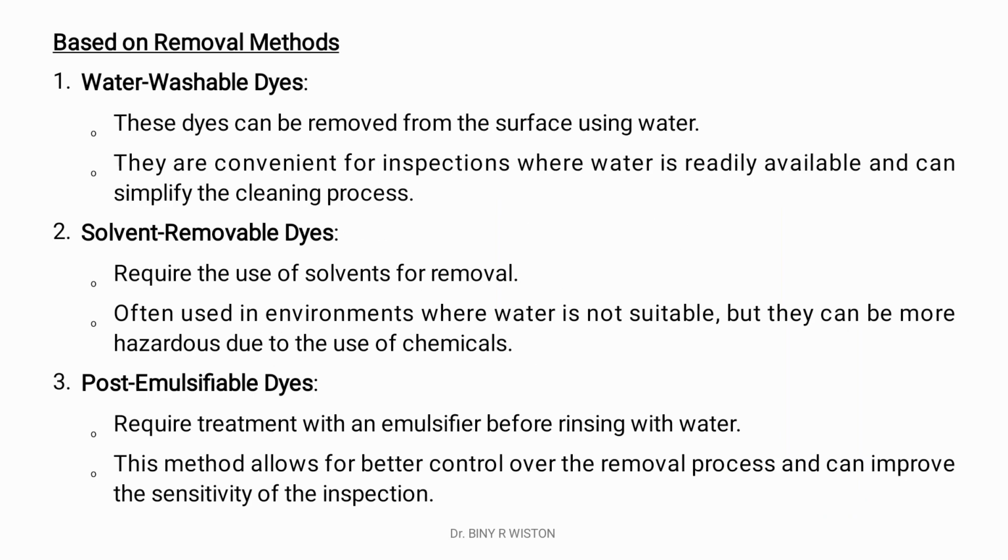On the basis of removal methods, dyes used in liquid penetrant testing may be categorized into water washable dyes, solvent removable dyes, and post-emulsifiable dyes. Water washable dyes can be removed from the surface using water.